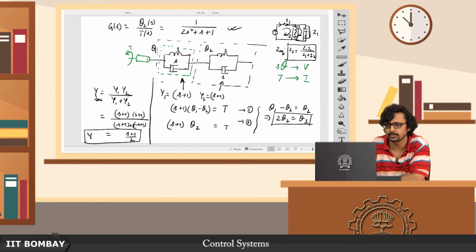This is the Z equivalent, and then you divide this voltage by this Z equivalent and you get your current, right? So here we are doing something very similar, only thing we are using current sources because that is closer to the physical world. We are keeping the through variables and the across variables intact with this notation, right? So now what do we have to do?